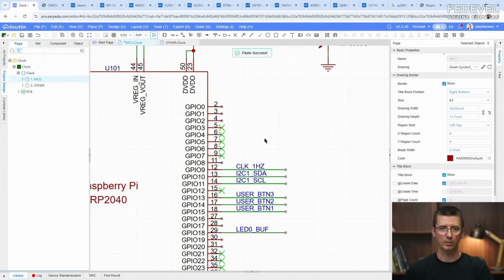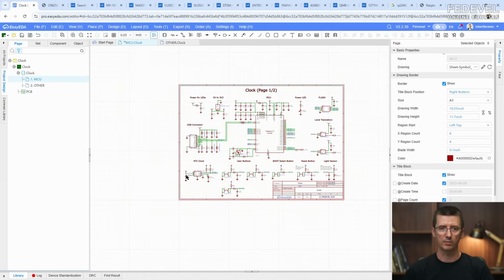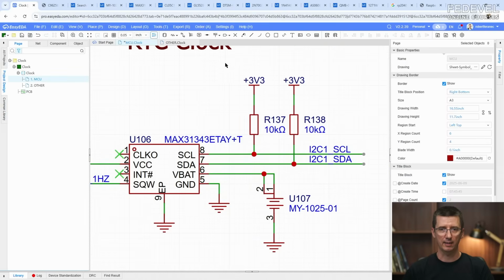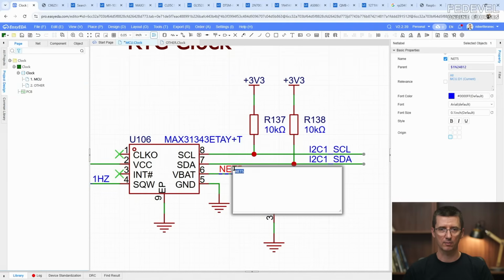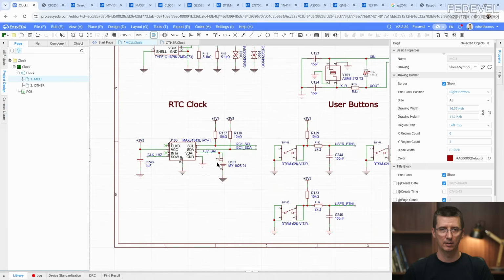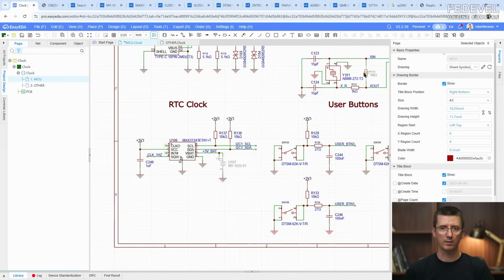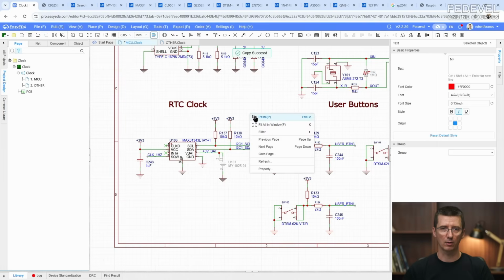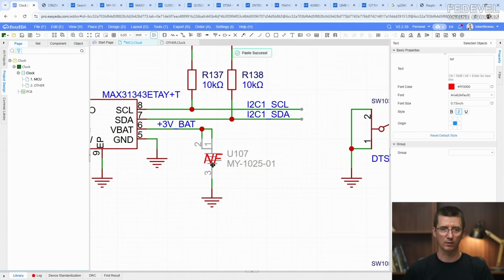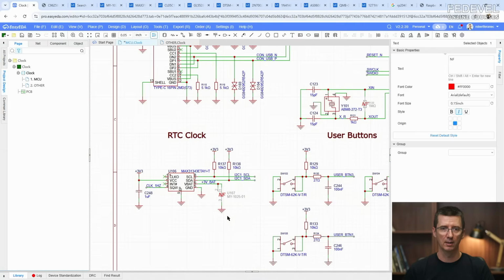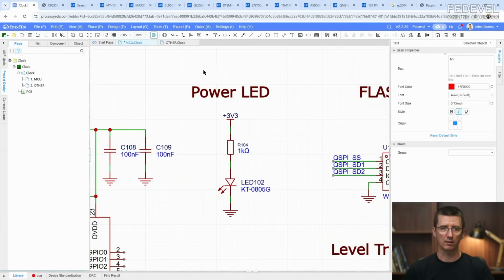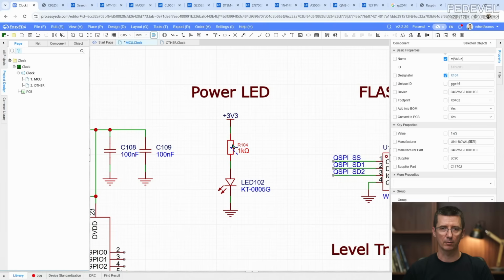It is not important which pin we will use because it's going to be standard GPIO. And I'm going to name this net because this is an important net. This is the battery power. And also I'm going to unfit this, because when we will be manufacturing the board, we would like to only fit components which are on one side of the board or on the bottom side of the board. If we ask them to fit both, then it would be more expensive.